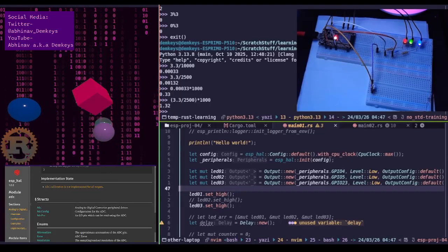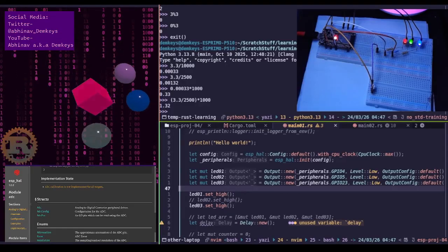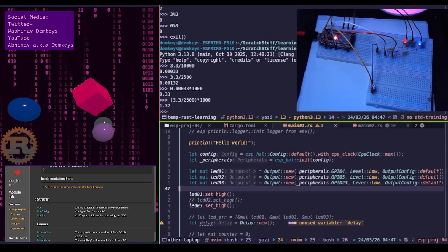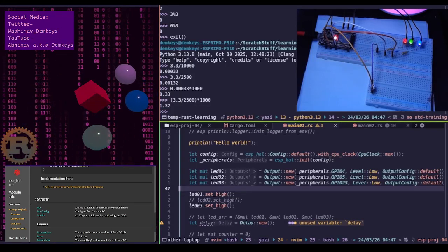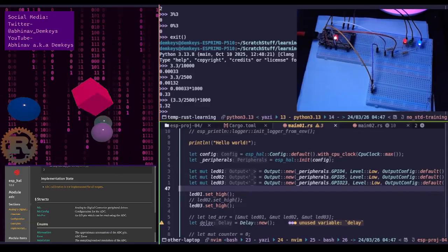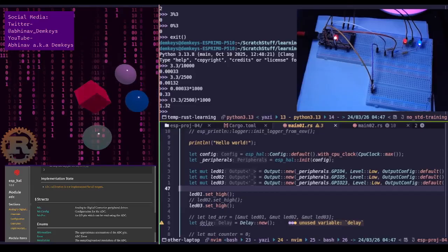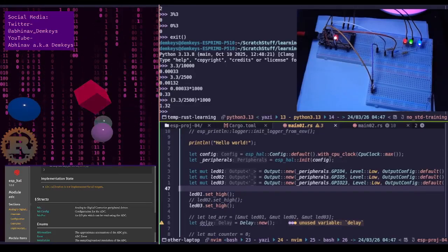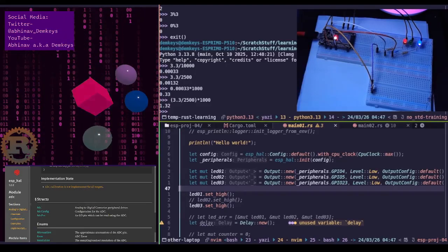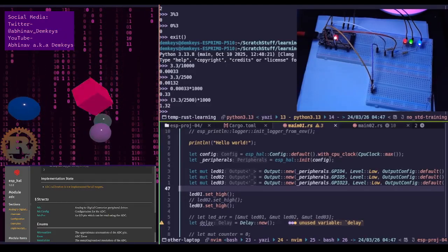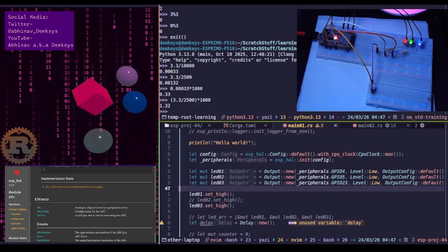The wiper is the magic shortcut. In your specific case with the potentiometer, you aren't physically grabbing two separate resistors. The potentiometer is the entire divider in one package. The top resistor is the track between pin 1 and the wiper, and the bottom resistor is the track between the wiper and the other pin. When you turn the knob, you are mechanically shrinking one resistor while growing the other. The total resistance, which is R1 plus R2, stays the same, but the ratio shifts.